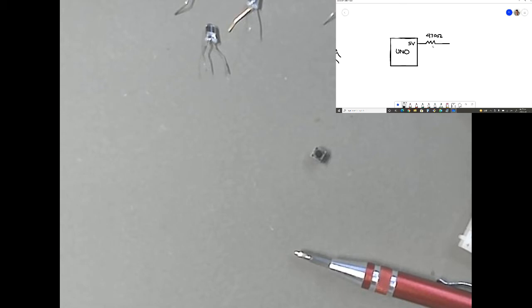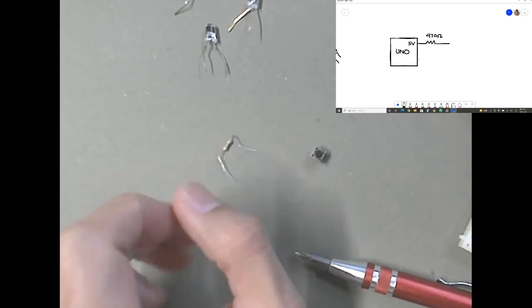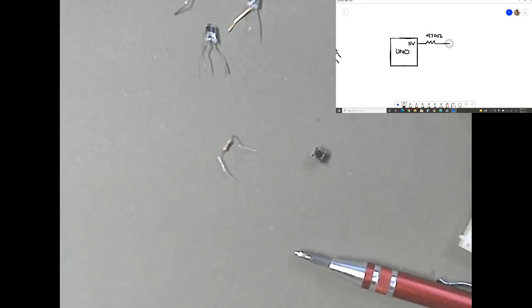An ohm is the unit for resistor. All right. And if you remember, 470 is the one without the red stripe, okay? The resistor without the red stripe. All right, and then we're going to do our light. Draw the plus and minus. And then this goes to GND. All right. So if we just do this circuit, we've done this before. Once we give it power, the light turns on, right? Now we want to make it a conditional circuit so that it only turns on if I press the button.